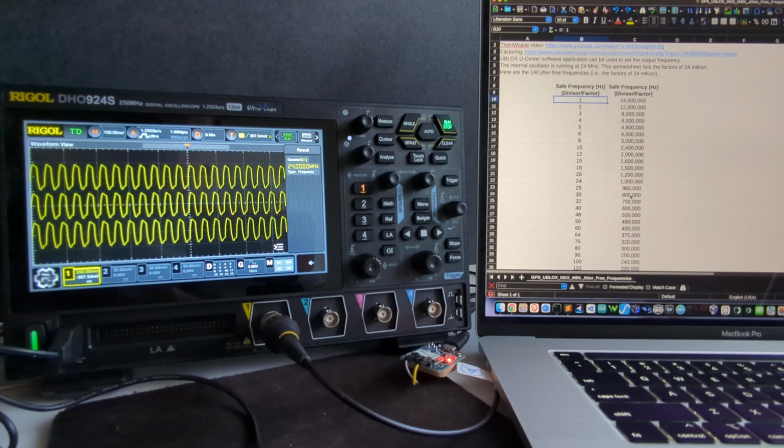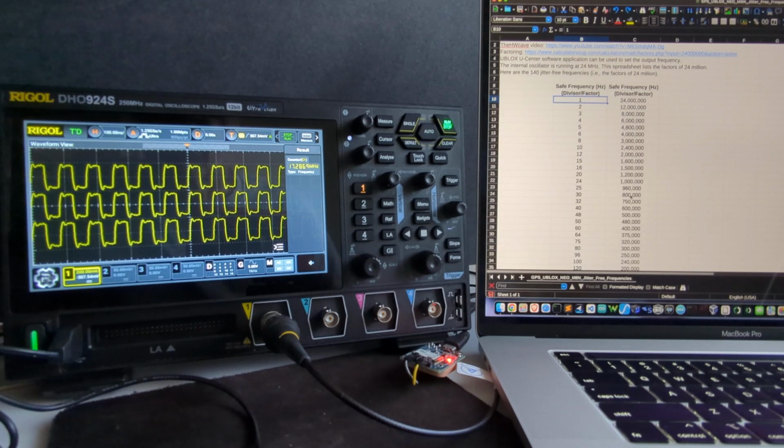I'll go down to 12 next. Just have a quick look at that. There's 12. And the next frequency that we would like, it'll be very useful for testing, for calibration, etc., is the 10 megahertz, and a lot of electronic units use it as an input, but it is not available. Obviously, 10 does not divide evenly into 24, so it's one of those frequencies that would result in glitches. So let's type that in and see what that looks like.